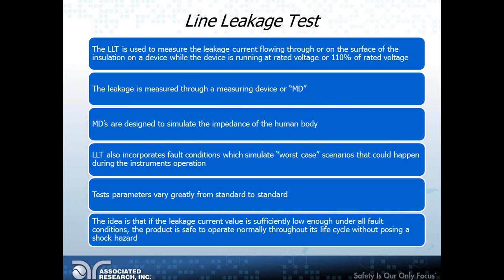Now, line leakage parameters can vary greatly from standard to standard. However, some of the most commonly run line leakage tests are for compliance to 60601-1, which is the safety standard for medical devices. For this standard, line leakage tests must be run at 110% of line voltage, and the acceptable leakage current values can range from 10 microamps all the way up to 10 milliamps.